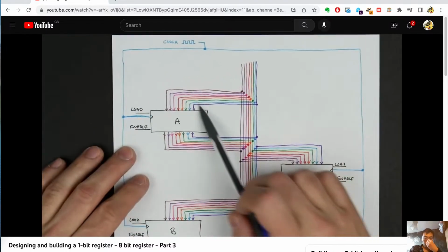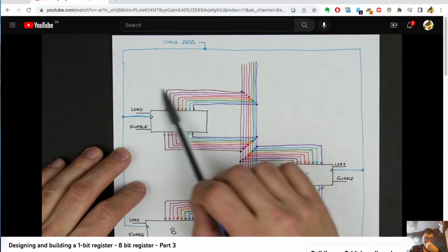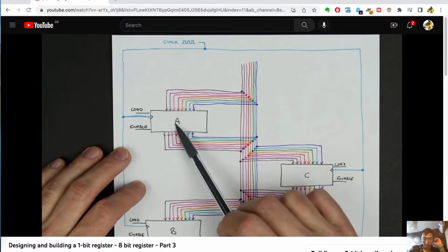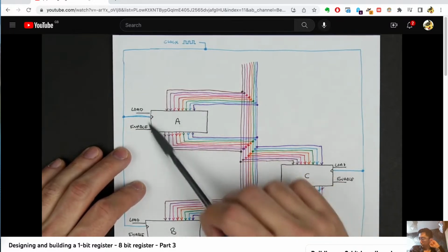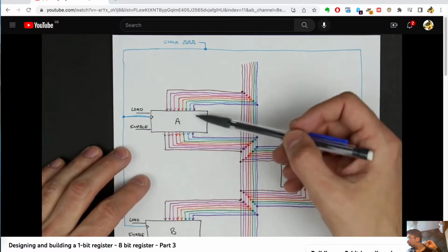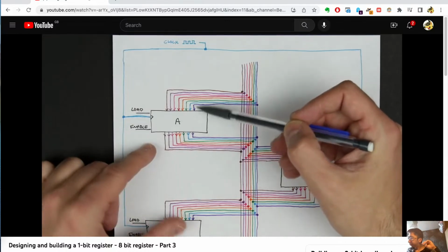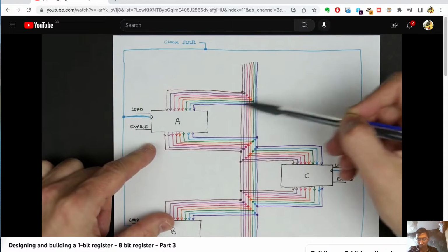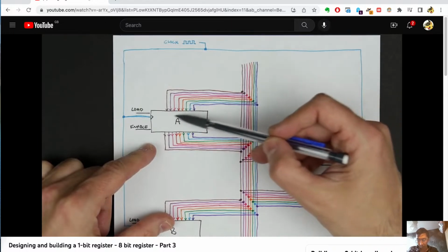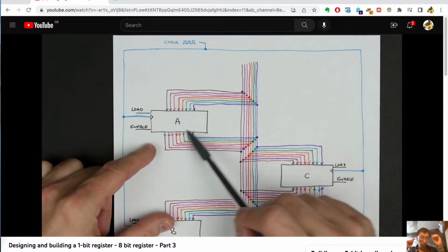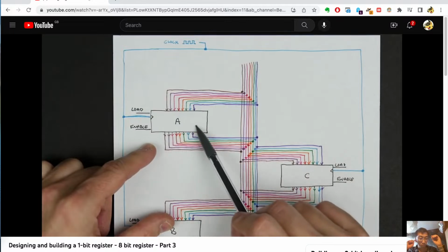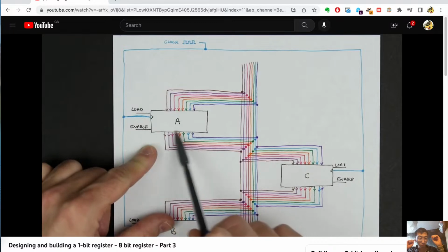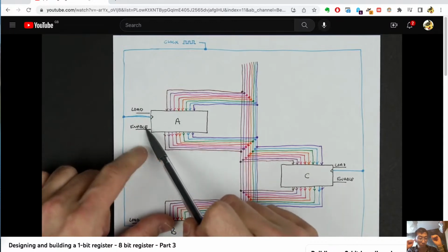So in this video, what I want to look at is actually what it takes to build one of these registers. In this case, we'll look at a register. These could be other things, could be input or output, but we'll look at building a register. And so a register, basically, what we're trying to build is something that has 8 inputs connecting to our bus that can store a value. So there's some 8-bit value stored in here, a series of ones and zeros, and it can send that value out to the bus when the enable input is high.